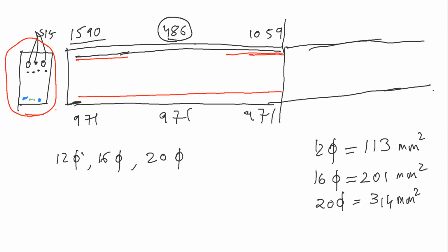This is called the beam, this is how every beam should be detailed in this manner. Okay, every beam should be detailed in this manner. Then if you come to the next beam, you can again find out the reinforcement over there, and the bar should continue on like this. This bar should continue in the next beam, and they should go on based on the reinforcement at the junction. That is beam detailing that has to be done. The software will give you the areas, but it does not select the reinforcement properly. It will do it to some extent, but the remaining part we have to do.